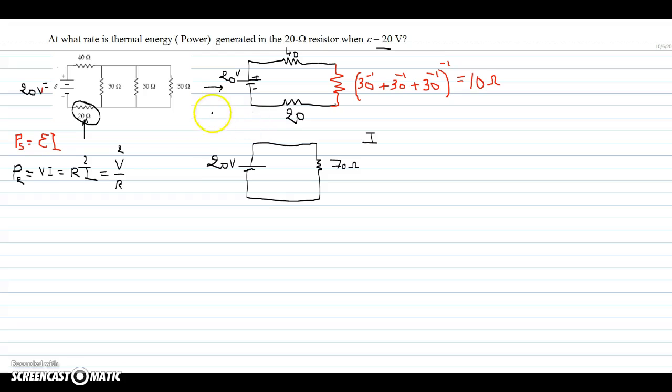Now we can add more questions. So what's the point here? What is the approach? The idea is to reduce this circuit to a very simple one with only the source and the equivalent resistance. Here you don't really need Kirchhoff because you have only one source. You can contract the circuit and extend it later if you wish.